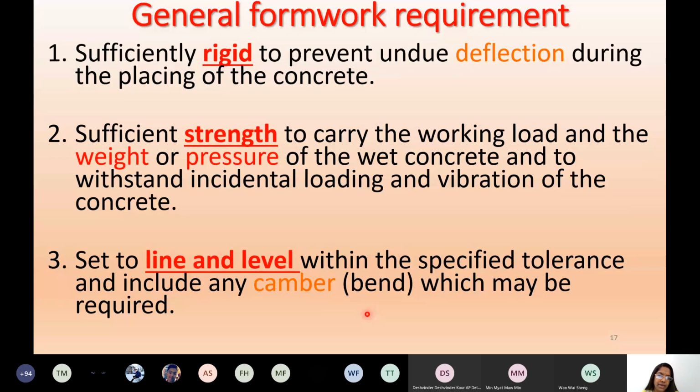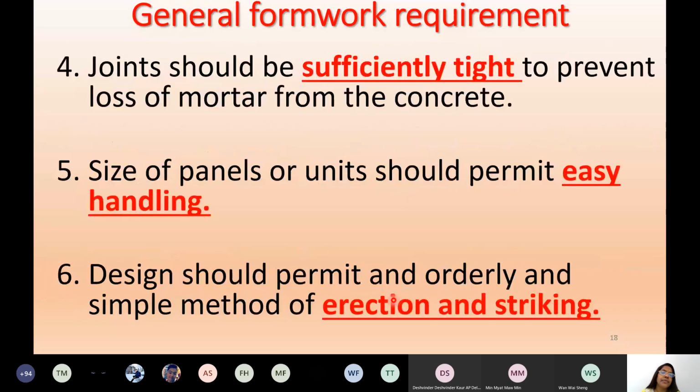Mathematically, you can calculate the diagonal, right? And then adjust according to the diagonal, using the laser level or plumb bob to adjust its height and the size of the cross section, so that you can avoid all these types of bending and non-collimation. Everything can be overcome.